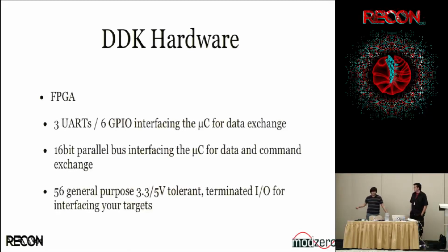And the answer is they want UART. Believe me, UART's the easiest thing. During the training, everyone wrote a UART in Verilog, and I think if you ask the people who took the training, they'll attest to how easy it is to write a UART on an FPGA. This is a perfect interface which is already there on the ARM, and on the LPCs you can clock it up to 3 megabits, and it'll do fine. So that's why we chose that.